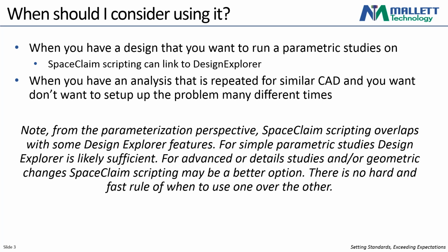When I've used it, it's been when the CAD geometry is similar enough that I can use the same script to create the geometry every time. However, I'm going to grossly modify the overall dimensions and maybe the response of the geometry I create. Then I may use SpaceClaim scripting to handle that operation, but have it linked to Mechanical without breaking any links or interfering with any of my loading conditions. So I will note here,